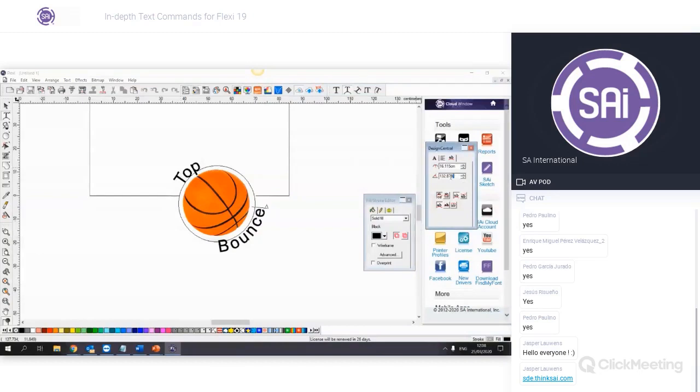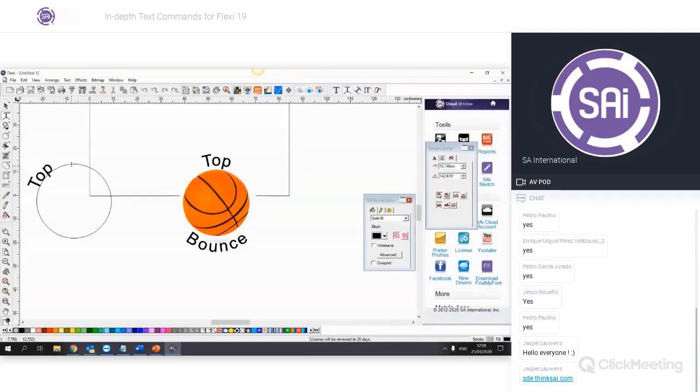And then I'll change my rotation here to 90 degrees. And that will format it from the top of my circle. So the option that I have selected here is for top and bottom style. So when I use this option, I can type the words top, and then anything else will be written on the top line. And then when I hit the enter button, instead of it dropping to a new paragraph or a new line, it drops to the bottom of my circle.